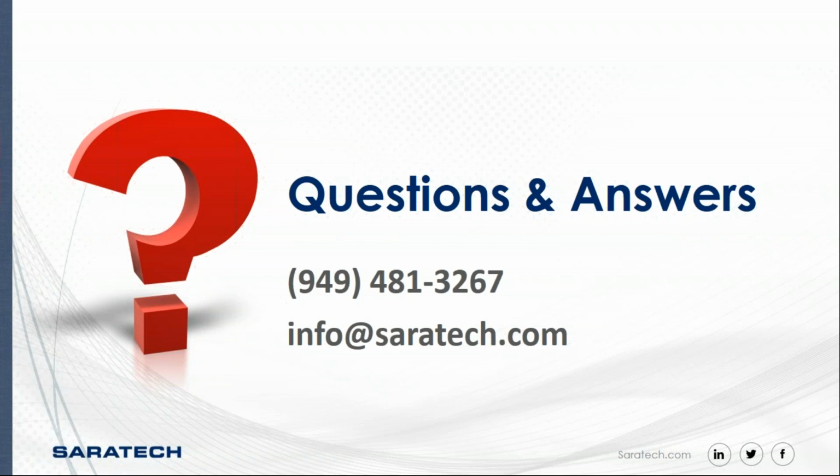So, things like the post-process technologies for support removals and the software generation for support creation and things like that in metals. And then as you look at new technologies, we can also help advise if it's potentially something you should wait on, depending on what your application is. So there are some new technologies coming out that are utilizing more of the metal injection molding techniques. That has benefits, but it also has drawbacks. So yes, there are new technologies, but there's a wide array of metals technologies that can suit your production needs today.